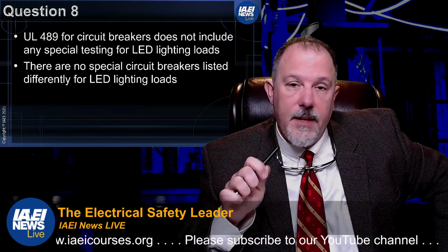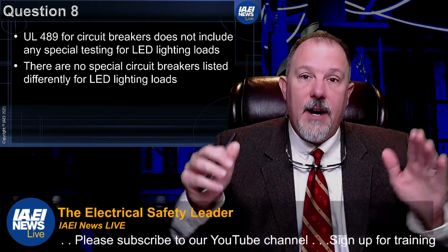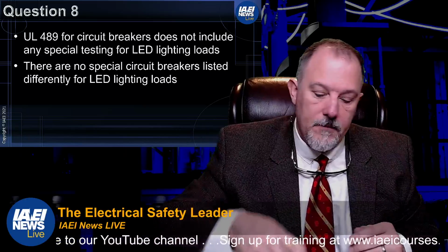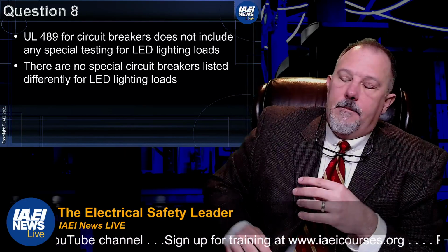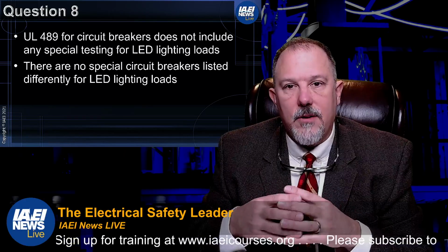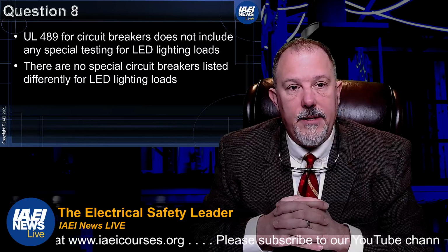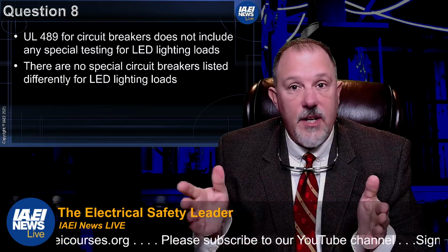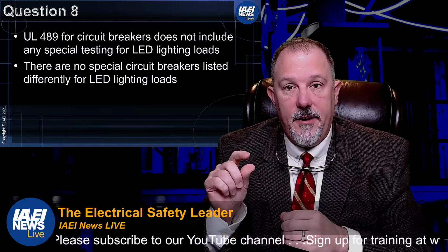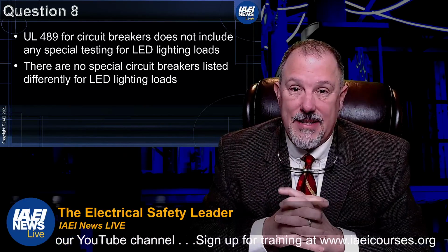It doesn't have anything to do with whether or not there were GFCIs in there. I've heard this on standard thermomagnetic circuit breakers. The reason is that these types of circuits will produce inrush currents, and they don't persist. They're short duration, but enough to trip a molded case circuit breaker on instantaneous.